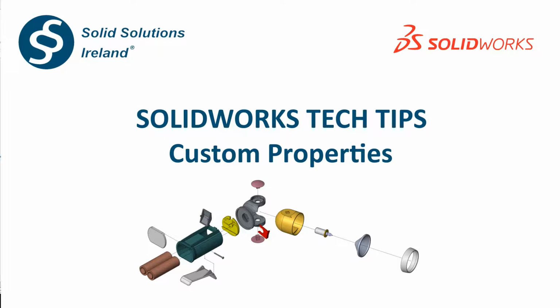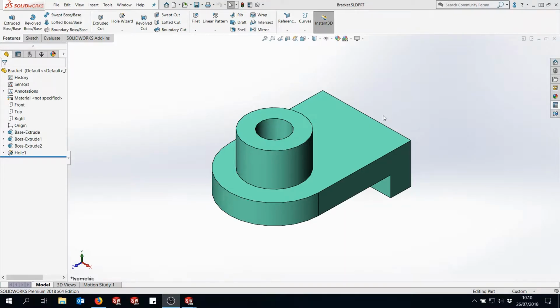Today I'm going to talk to you about using custom properties inside of a SOLIDWORKS part file. Custom properties can be used for different things such as storing metadata of SOLIDWORKS parts, using that data to populate out title blocks on your drawings, or using that data in PDM to fill out your part card or your folder card. To access your custom properties, you've got two main methods.